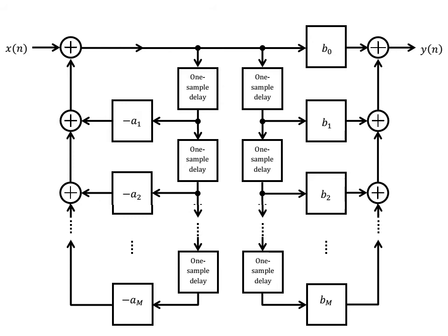An interesting thing is that we have these one sample delay units operating in parallel. The two vertical columns of delay units are essentially storing the same delayed samples, and in one case feeding them to the left and the other feeding them to the right. So they may be combined into a single chain.